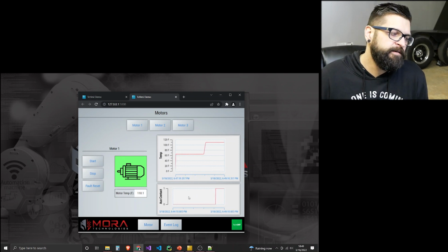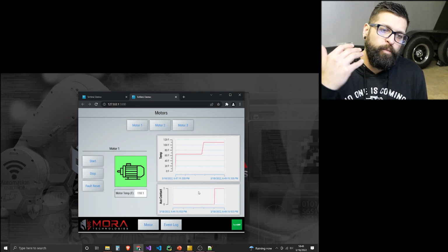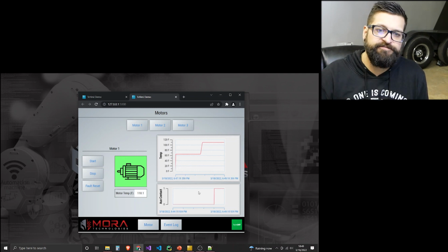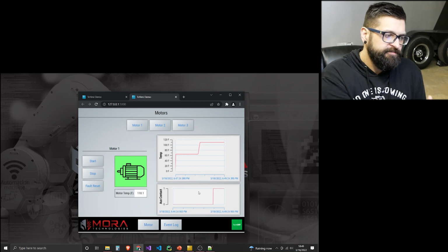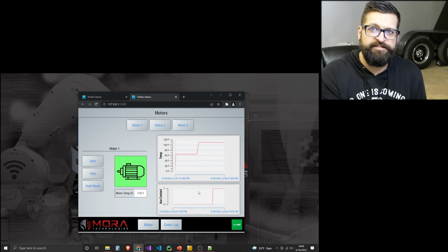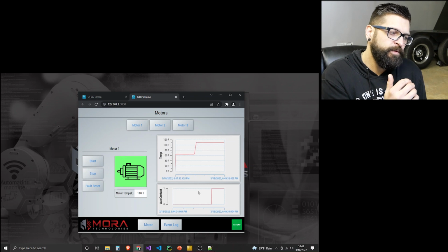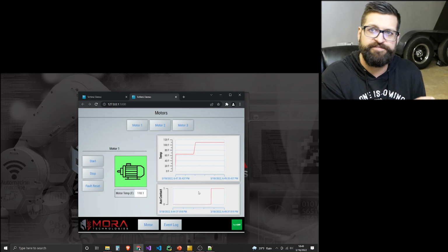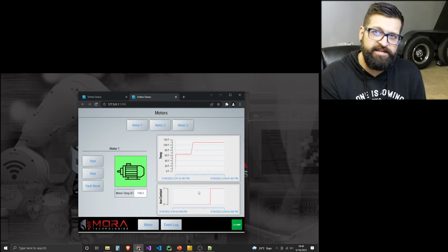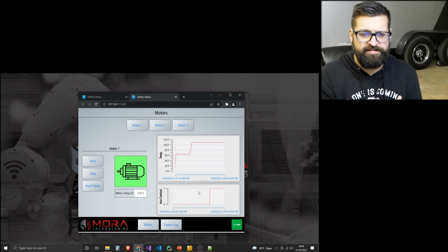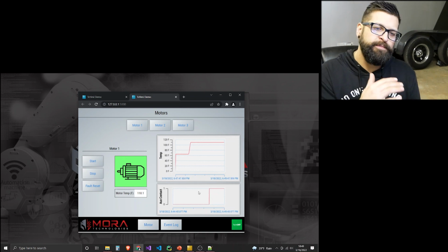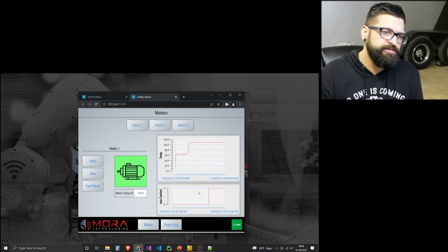And this is really more just to show you how you can use templating and indirection through buttons to create one set of objects and then pass, just like in function blocks, different data through them. So if you've got 3 motors, you don't have to create 3 content files, one for each different motor. The idea is we want to reuse as much code as possible so that we cut down on our development time, and so we don't get into the rabbit hole of copying and pasting things and mistyping when we need to edit something that we've copied, and it makes troubleshooting easier.